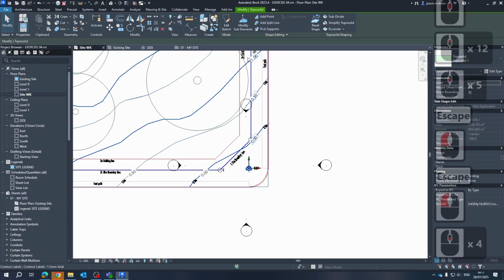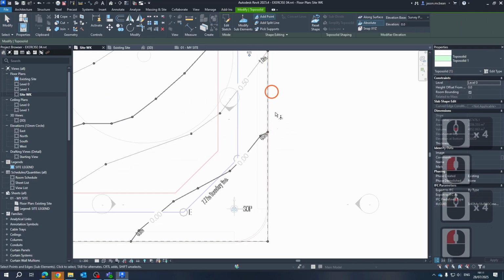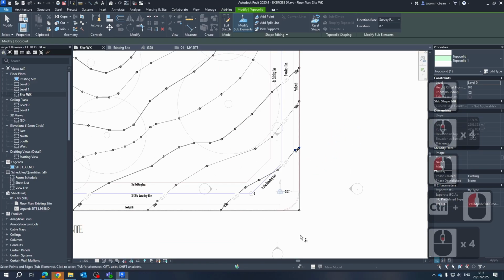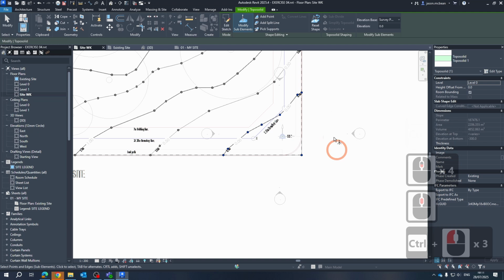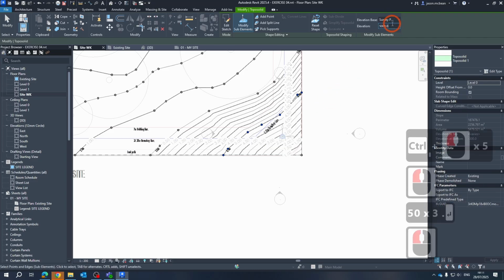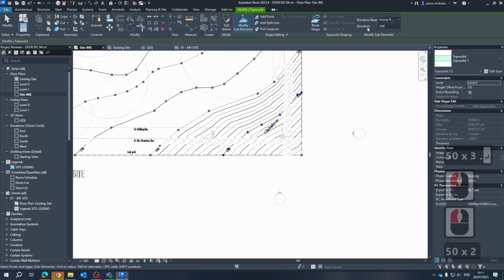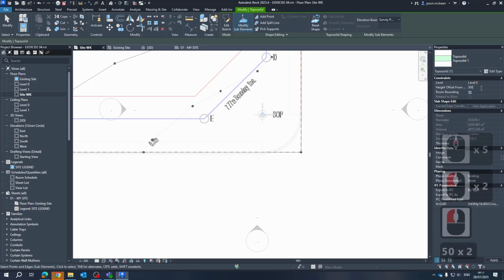So to fix that, you have to go to modify points. Now use control and you select these points over here, and you just need to make sure that the right points have the right level. This did it to me. So typically, I think this is a bug of this version of Revit that we're using. So typically in the past that would not happen. So just make sure that the levels are correct. Okay. I suppose we could keep that offset at 500.